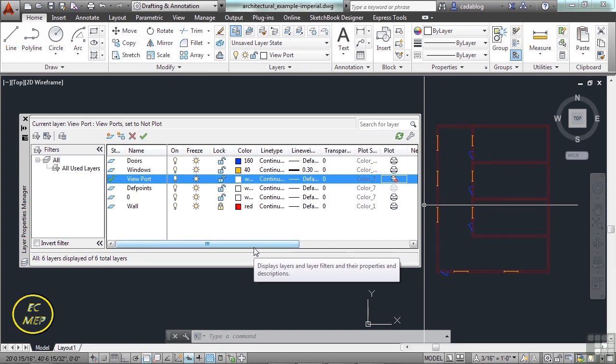So let's say you've done your project, you've submitted it in, and now you're coming back with a change, and you don't want it to show up in your other drawings by accident. So you put it on a new layer, and you say new viewport freeze. So anytime someone makes a new viewport or it comes in, it's not going to be turned on. It'll be off, so the line work won't show up.